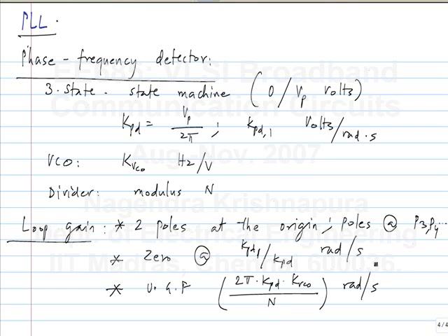And typically, in a frequency synthesizer, n has to be variable. That is, you may have to generate different frequencies from reference frequencies. And in some cases, the same system may have to operate with different reference frequencies and give out the same output frequency. Okay. So, this depends on the system. For instance, you use a sound card, and in some systems the sampling rate is 48 kilohertz, in some it is 44.1 kilohertz and so on. So, you can't expect the external system to always give you one particular frequency. Whatever it is, you are expected to use it and generate the right frequency for your use inside the chip. We are not talking about sound cards, but the idea is similar. If you have your Ethernet card plugged into something, the reference frequency available may be different if you plug it into one PC or the other, or some platform and some other platform and so on. Okay.